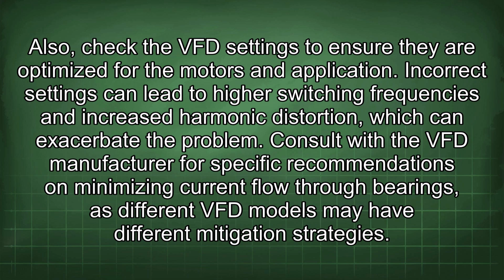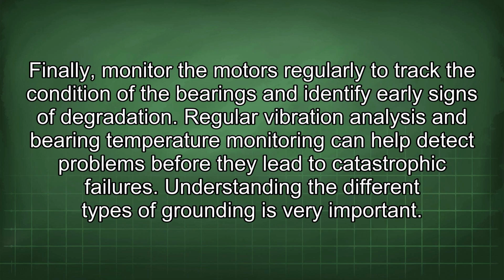Consult with the VFD manufacturer for specific recommendations on minimizing current flow through bearings, as different VFD models may have different mitigation strategies. Finally, monitor the motors regularly to track the condition of the bearings and identify early signs of degradation. Regular vibration analysis and bearing temperature monitoring can help detect problems before they lead to catastrophic failures.